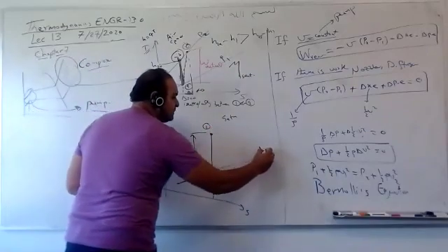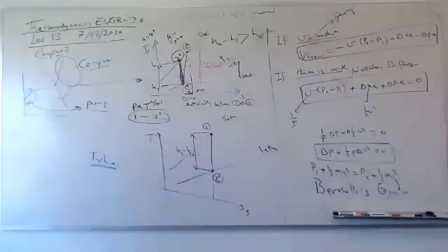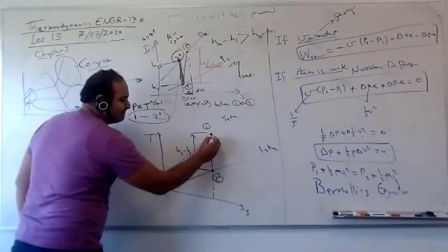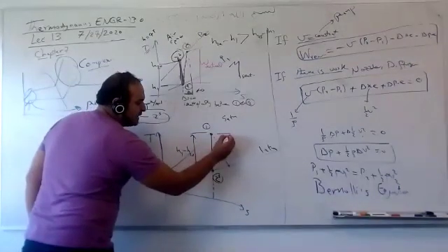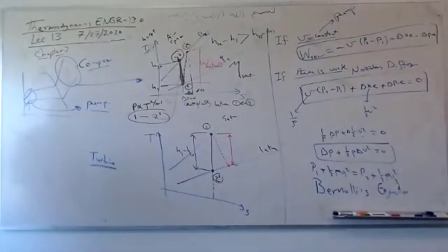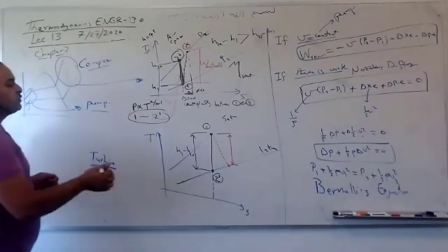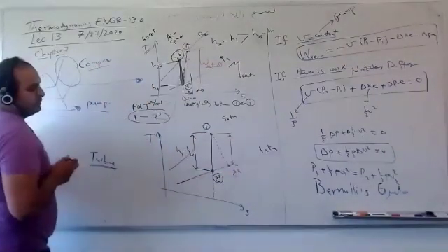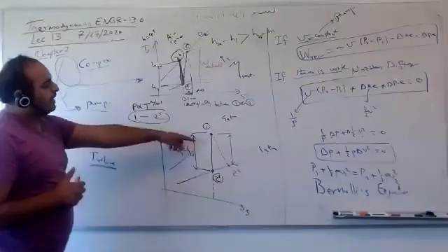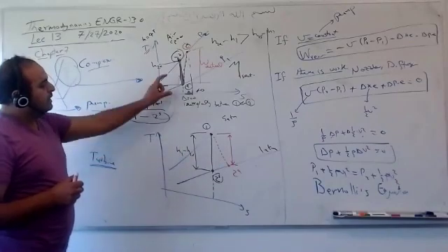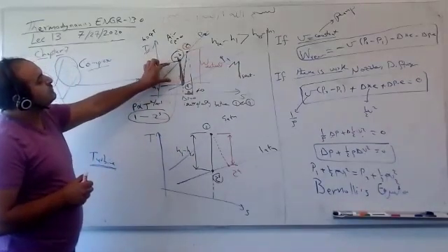It goes from high energy to low energy, from high pressure to low pressure, expanding through the turbine. But what happened in reality? The red line, I have delta S, some losses. Which one is taller, guys? The red line or the black line? The black line, of course. What you get isentropically is more than what you get actually, h2A. Opposite to the compressor, here I get less than what I'm supposed to get because of losses. There, I pay more than what I'm supposed to pay because of losses.